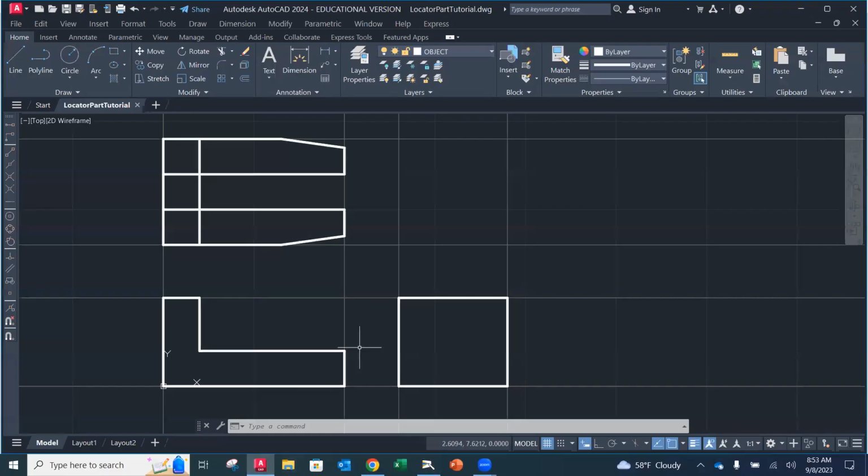So if we go back to AutoCAD, what we're going to do is place that circle, and it's going to be center diameter. The diameter is going to be 1 inch, and we need to put it right in here at those coordinates. Whether you pick the bottom left-hand corner or the upper, it doesn't really matter, but we're going to be in the middle, 1 1/2 from either side, and then from that edge, 2 1/4. I did my circle command already. It wants to know where my first point is. I want to snap from, and I'm going to pick my lower right-hand corner of that view.